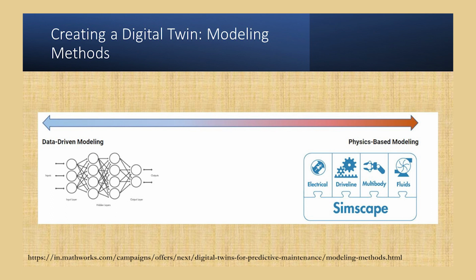An example of that could be an electro discharge machine, an EDM. In an electro discharge machine, you have many different operating parameters such as the pulse width, the current value, or the electrode material. Those are the inputs, and based on those inputs you get an output which is the material removal rate, let us say. What is my material removal rate at 10 amperes? What is my material removal rate with 25 microseconds of pulse width?